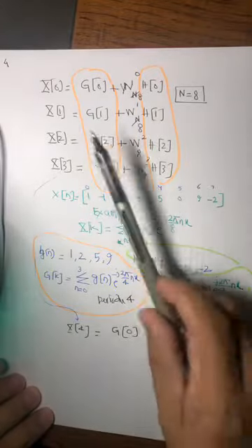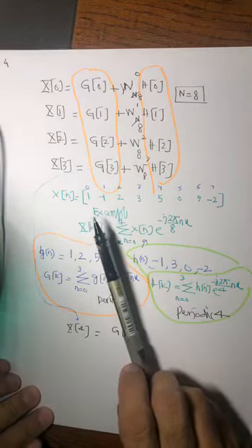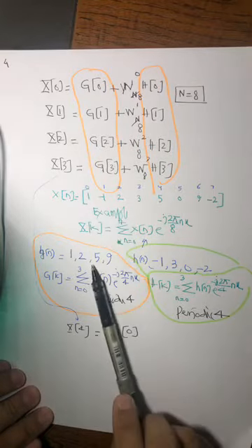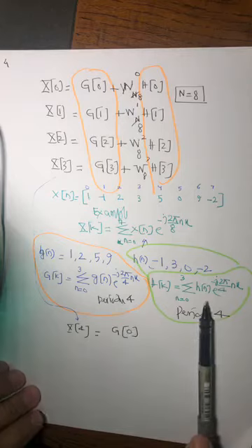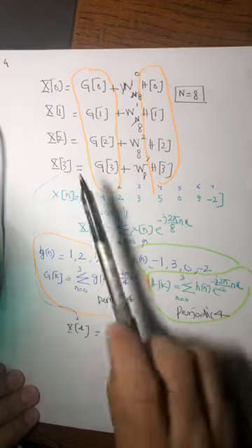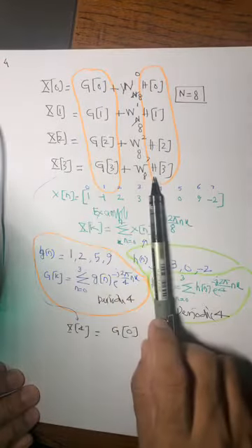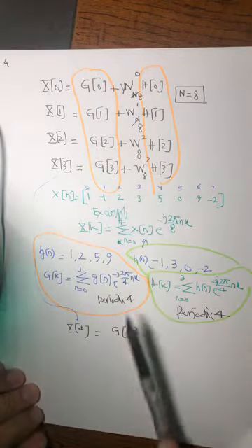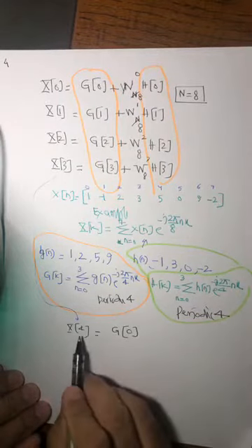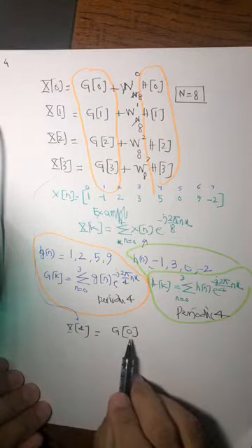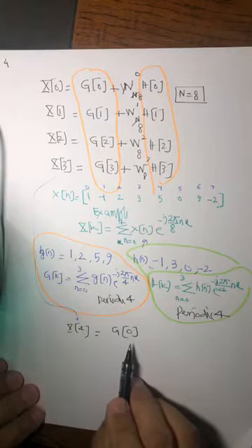So you split the DFTs into two parts. Use half of the points here, half of the points here, and you take N by 2 point DFTs. It's very simple to understand. And then you combine, and once you are combining to get an 8-point, you don't get any saving at first, but where you have the fourth index, because G4 is the same as G0, you don't have to recalculate this, and this is where the savings are.